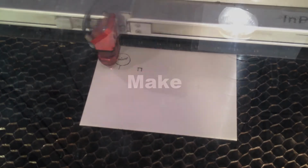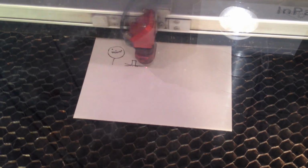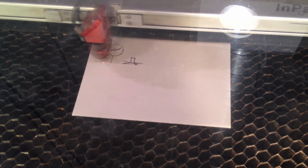Here's video shot at TechShop of the laser cutter in action. It is etching away at that top color of the mat board and revealing the undercolor. As you do this, you need to follow the laser cutter instructions and follow the right power settings for different materials. Obviously wood requires a different laser power setting than paper, for example. So just use trial and error and follow the directions.